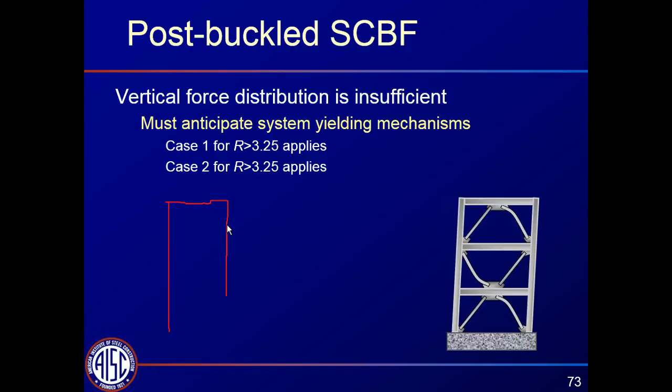The first one, I'll make it fairly simple. The first one tells us to look at the maximum tension and the maximum compression and figure out what's going on in the columns. This will give us the maximum overturning, and what's going on in the beams. Then there's a second analysis, and that tells us to look at the maximum tension force again, but look at compression being degraded to 30% of the maximum compression capacity.